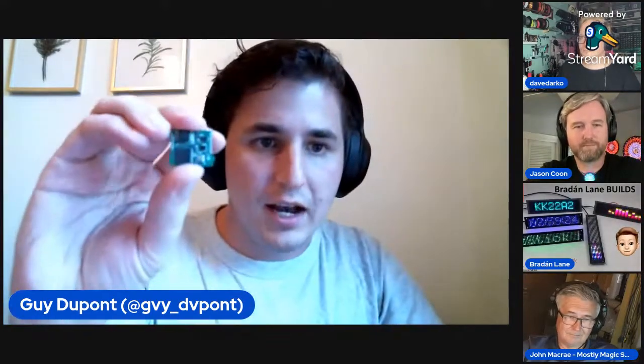This version is running an RP2040, and I'm using the PIO from the RP2040 to drive the actual audio. Otherwise, it's just running CircuitPython, because all it's doing is reading the media off the flash and turning it into the audio PWM. It's a really nice combination where I get the fast output from the PIO, but I get to use with file.open to get the data out. So that's nice.